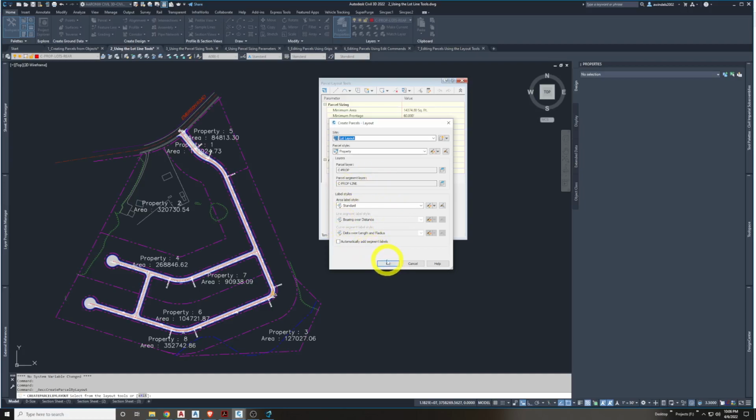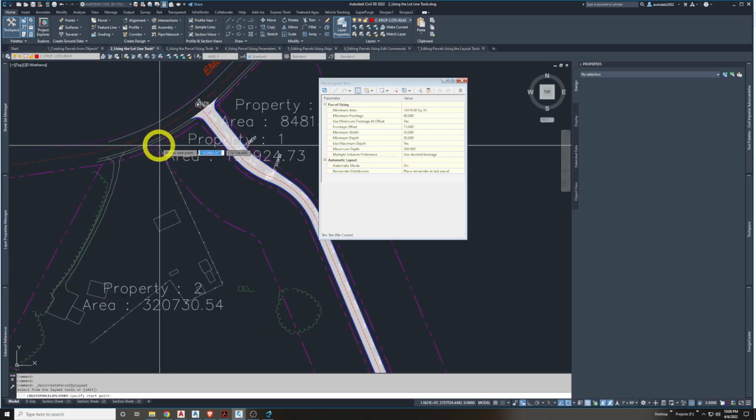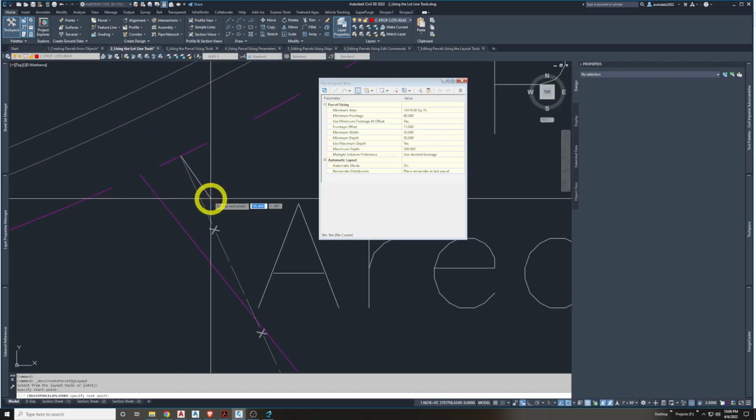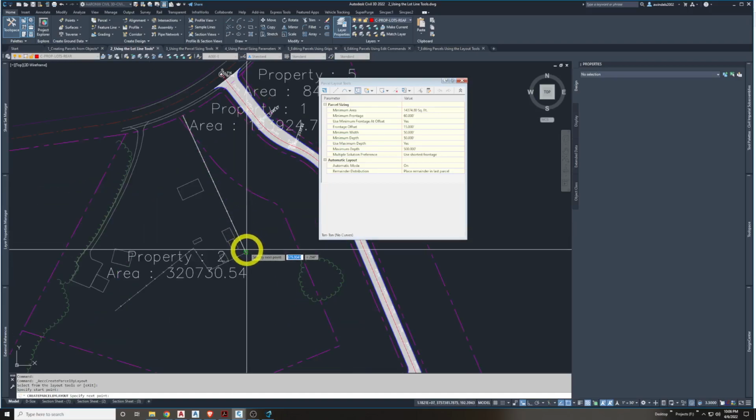So once again, let's just hit OK to accept all this. And I'm going to go in here. We'll start at the north end of the fence and work my way to the south and to the west. So let's pick right here, where the fence hits. And let's just have our endpoints pick on our O-snap.